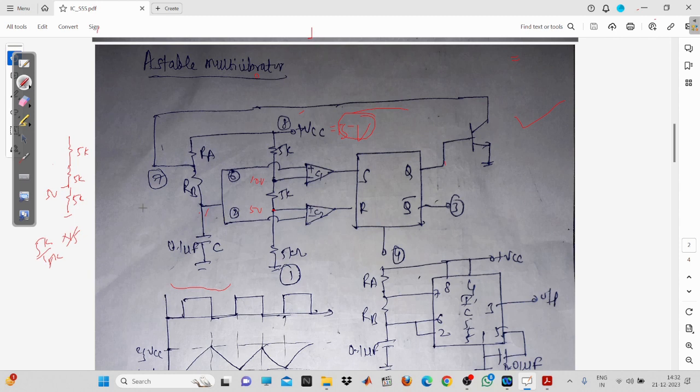Fine. Okay, so initially there is no voltage across the capacitor, as you know the capacitor is initially uncharged. We have just bought this capacitor from the market, and we'll try to do some experiment on the 555. So basically this voltage will be equal to 0. The voltage given to the sixth pin will be 0 volt. So a 0 voltage will be here only. I think it is properly visible. So 0 volt, 0 volt.